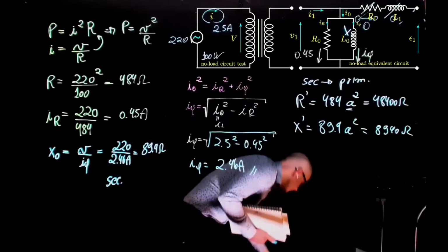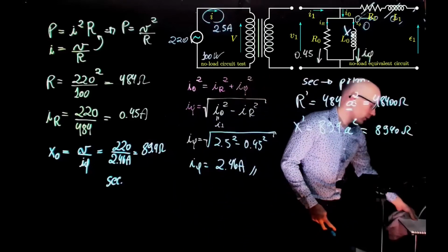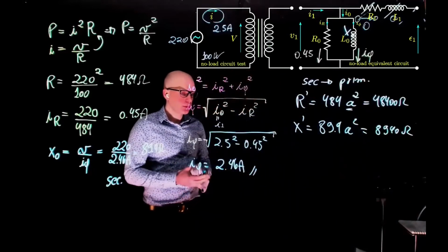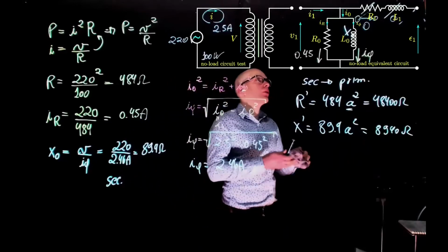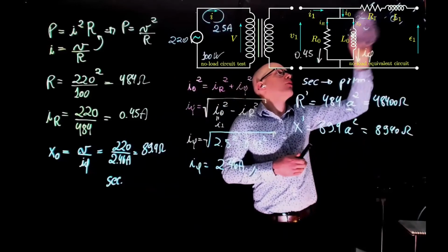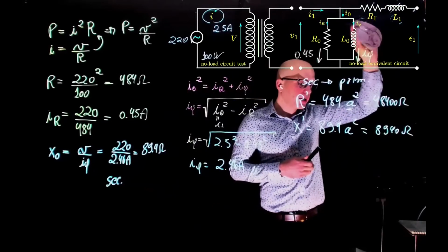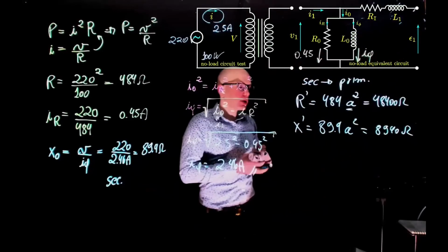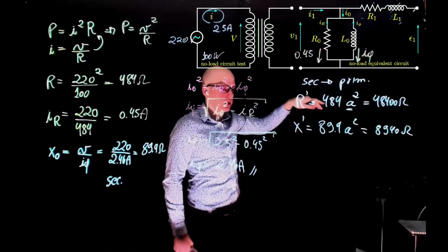Any questions here? Sorry, could you go over why R1 and L1 are ignored? Yeah, sure. We see that we are leaving one side of the circuit open. So it's just because it's open. So there's no current going that way, so they can be neglected.